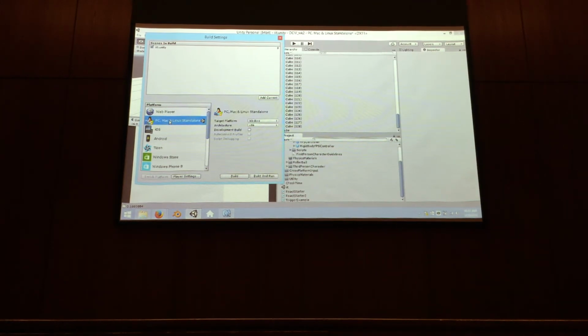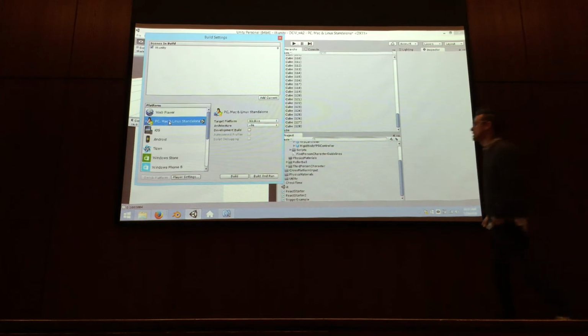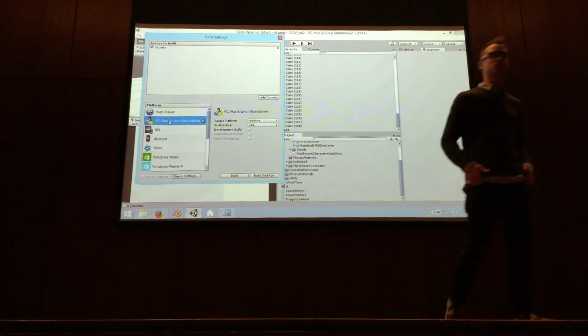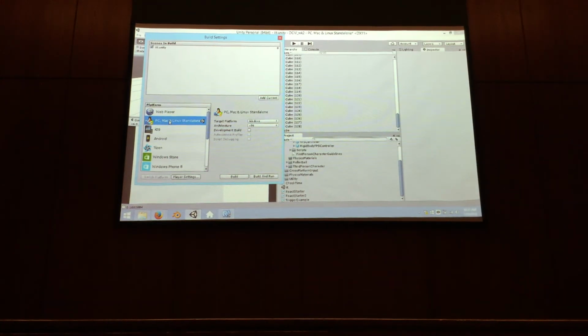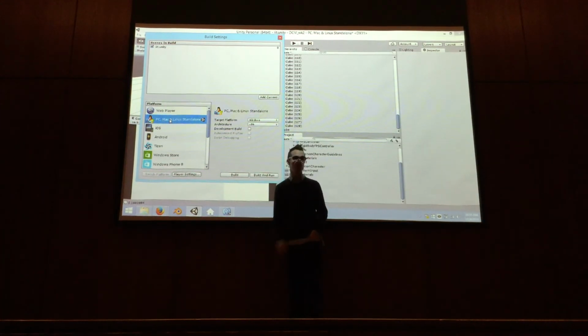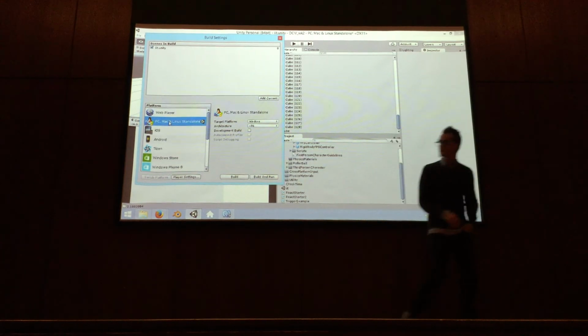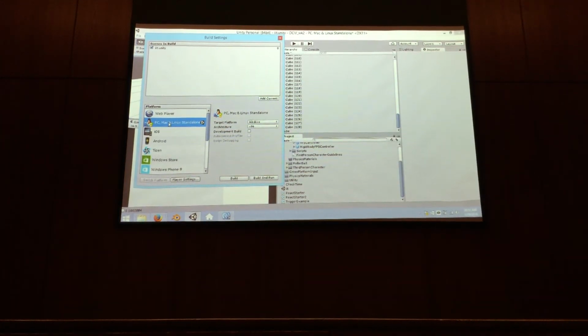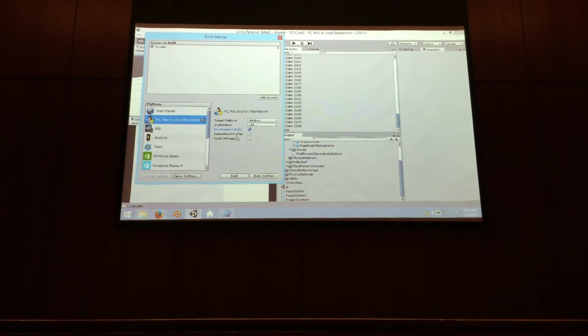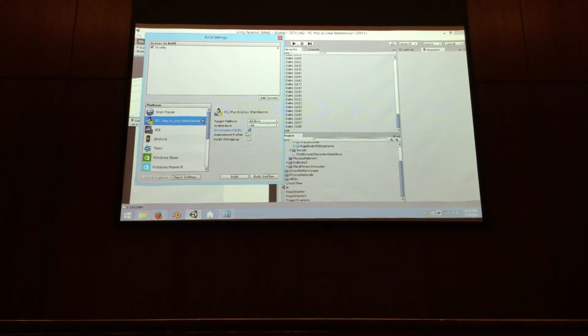And then, of course, you need to pick your target platform. We would like you to pick Windows. If you have a Macintosh computer, you can publish to Mac and run them locally, that's fine. But when you submit your homework, you should submit using Windows, okay? And then platform x86, that's fine. Development build: by checking development build, it gives us a little bit more access to troubleshoot when things are not working right. This isn't requisite, but it's fine.